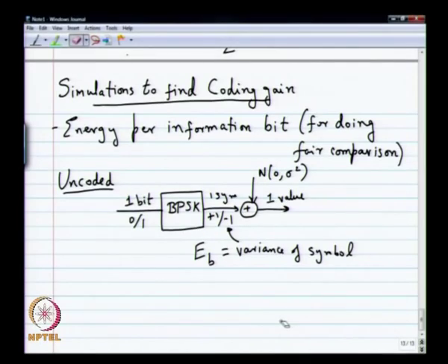When you take waveforms and define a basis and convert them into constellations, the energy in the waveform corresponds to the magnitude square of the vector. If you remember your digital communications well, in the vector space representation of signals, the energy in the waveform, that is the integral of |x(t)| squared, is the same as the norm squared of x.